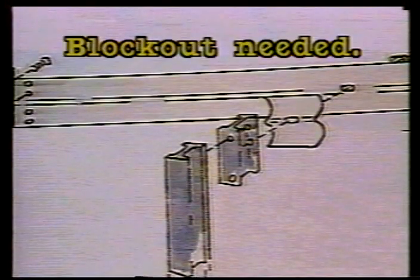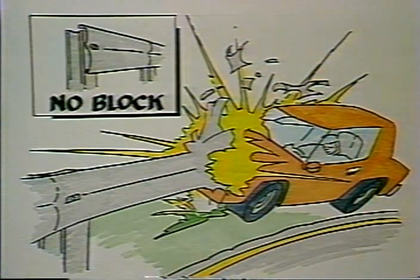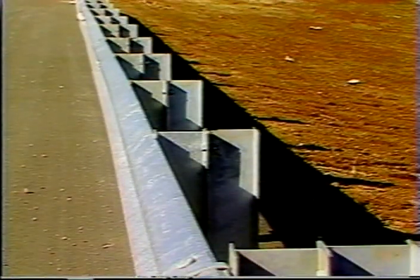The offset block or block-out sets the rail 6 inches out from the face of the post. Many early guardrail designs were not blocked out, and this caused some problems. When a vehicle hits a rail that is not blocked out, the impact will often flatten the rail. Instead of sliding along the face of the rail, the vehicle will penetrate beneath it, snag a wheel on a post, and spin out onto the roadway. The addition of the block-out will help prevent this problem in most situations.